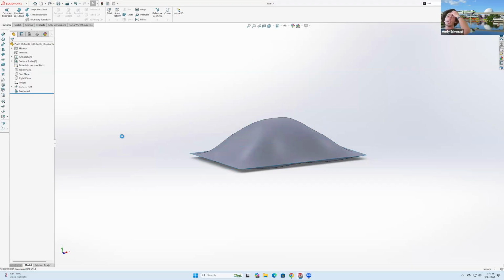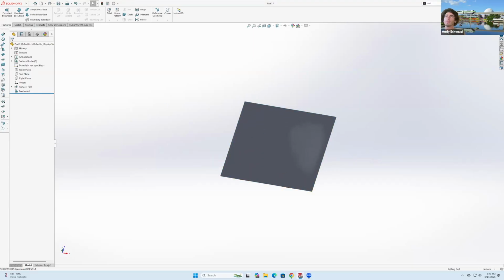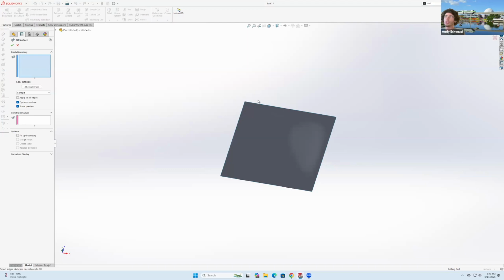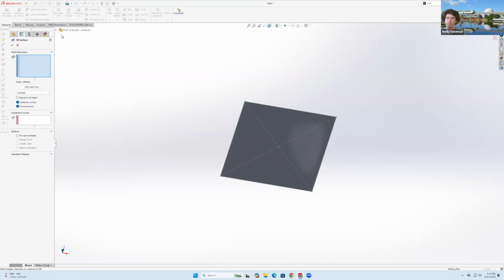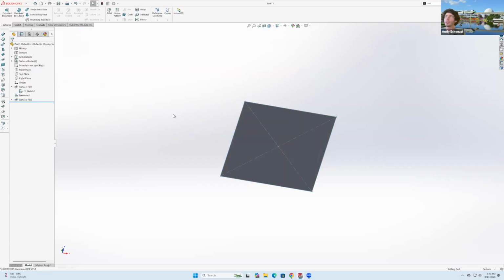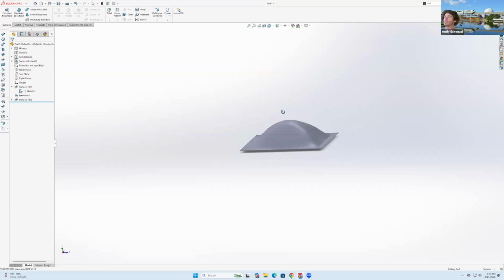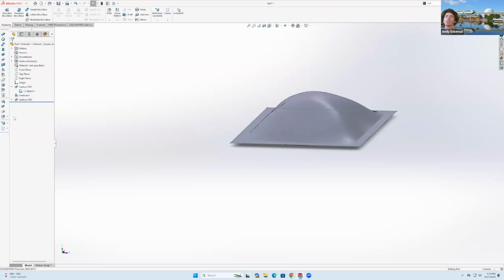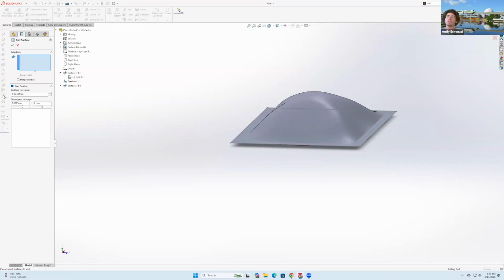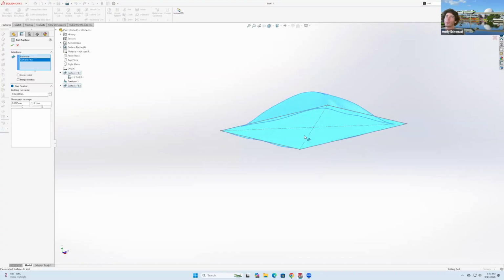Okay, what I could do is maybe another surface from here. No, let me see if I can show that sketch again. There we go. I'm gonna go to fill the surface, perfectly. So now it's this surface on top, like the ravioli, and then the bottom in there. So then you can go over to a command that's called knit surfaces. And I can click on this one, I can click on that one, and I'll say merge entities and create a solid.